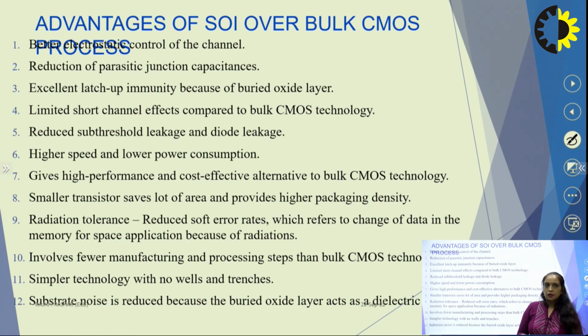The advantages of this SOI technology over the bulk CMOS process are: we have better electrostatic control over the channel, reduction of parasitic junction capacitance, and excellent latch up immunity. We have seen that with the help of the buried oxide, your VDD and VSS are completely isolated from each other.